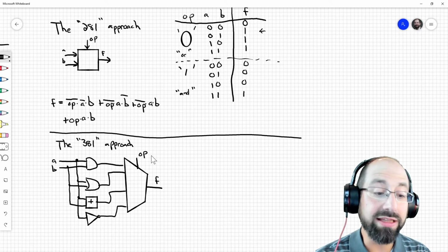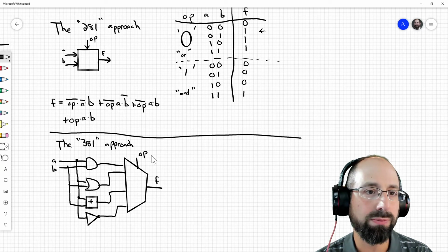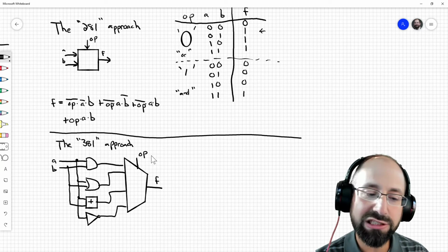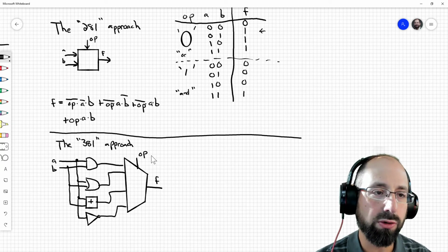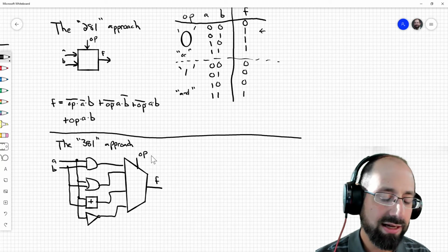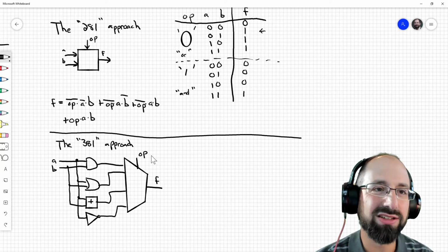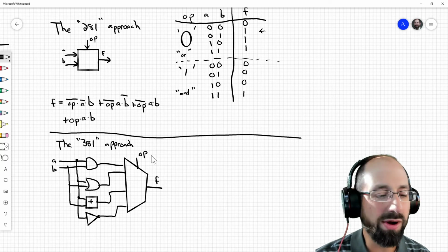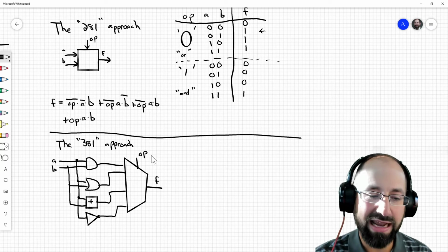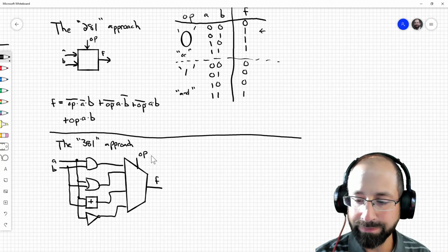representation. I believe, although it would take quite a bit of time to prove this from base principles, from a hardware realization perspective, just comparing the AND OR circuit here to the AND OR circuit here, I believe they're equivalent. I believe the mux itself is also just gates, and the resulting operation is going to look a lot like this, that there's a value for when the mux input is 0 and a value for when the mux input is 1. And that corresponds to AND and OR gates anyway. And you wind up getting the same exact identical circuit back out.